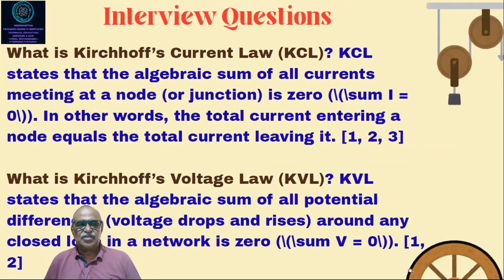So again, in the interview, they may ask you what is Kirchhoff's current law, KCL, and what is KVL. KCL states that the algebraic sum of all currents meeting at a node or a junction is zero. Suppose we take currents: IT minus I1 minus I2 should be zero. That is what you have to understand.